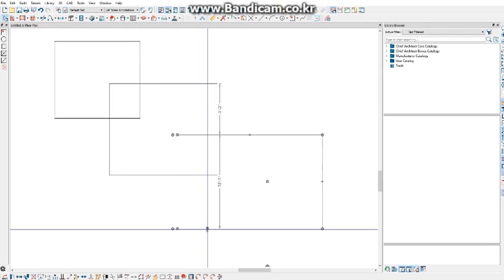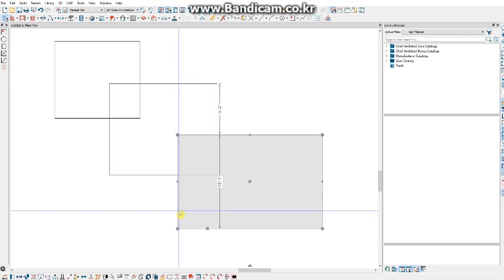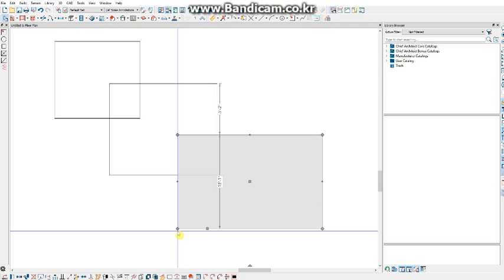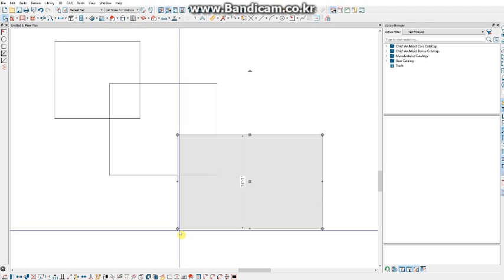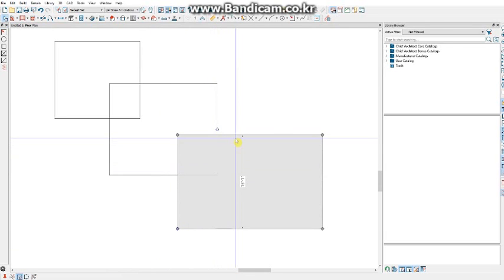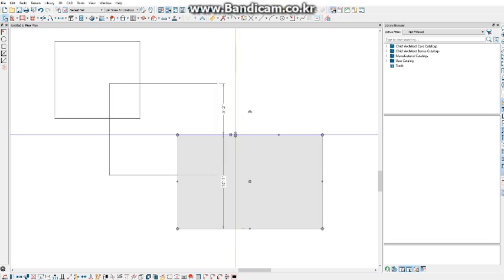If you have a polyline but it's not closed, you have an option here to close the polyline. That will simply add one more line segment connecting the last 2 end points. Another edit tool you have in your toolbar is your Break Line tool. This allows you to break any line and create 2 separate line segments. I'll go ahead and click on the Break Line tool and then click along any one of the line edges.